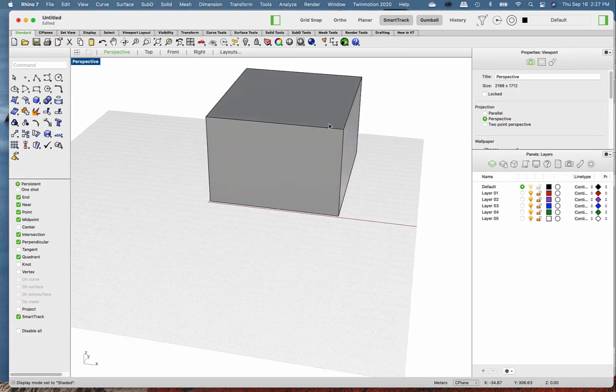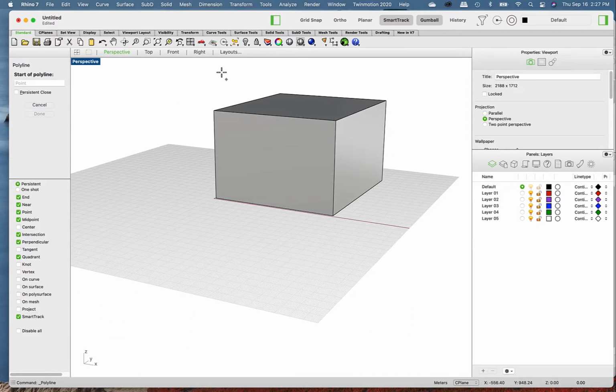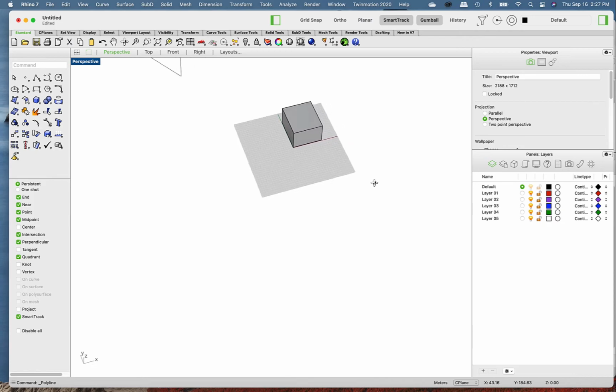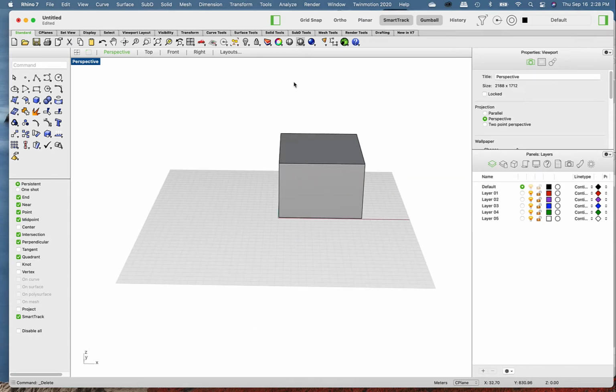chimney on the top of the box, but like I said, if I'm in perspective view and I don't have the snappings properly turned on, if I think that I'm clicking on one part and start drawing whatever, it's likely going to be way off into space, not where you had intended it. So you can actually use cplanes to take advantage of the surfaces that you have here.